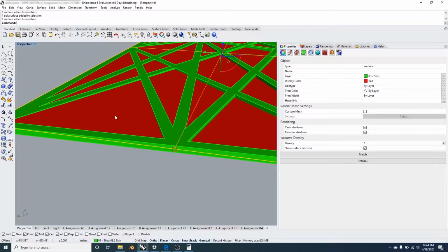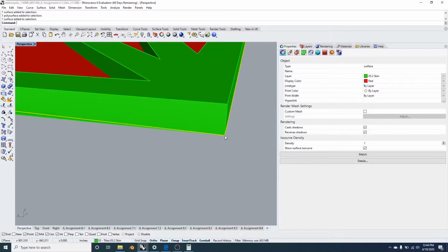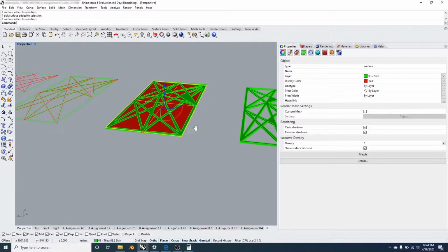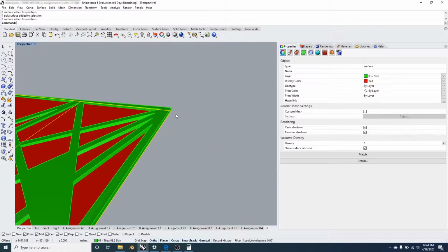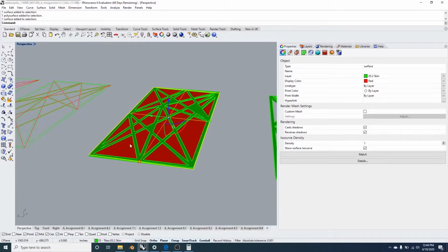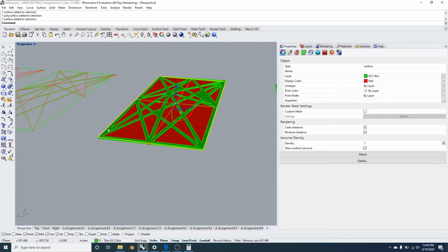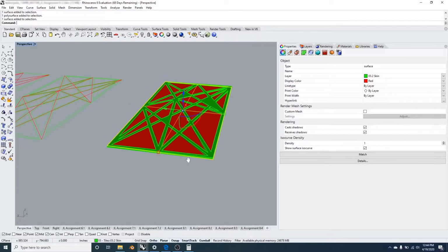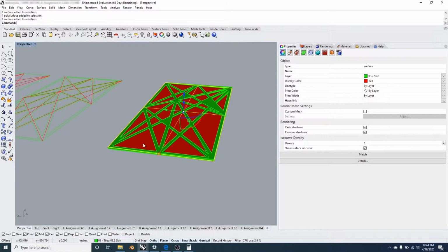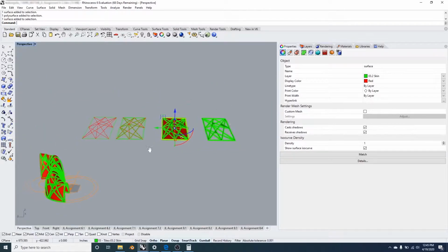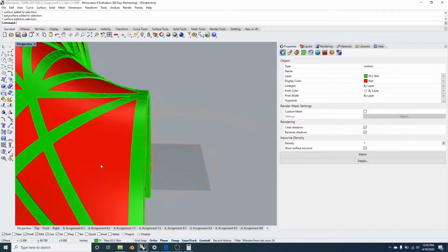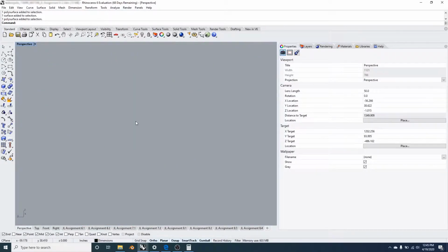When I select this plane, you can see that one end is on the underside of the panel. The other corner is on the other underside of the panel as well, whereas the other two corners are on the upper side of the panel. So now Rhino is interpreting this as the correct plane to use, and then it's extrapolating to the target plane. That's why you're getting this result that we explained.